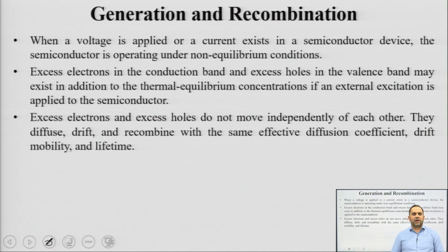Our discussion till now, whether related to carrier concentration evaluation, identifying the current components, polarity, or mobility, has focused on the condition of equilibrium. When we mention equilibrium, we are generally talking about thermal equilibrium, where the semiconductor does not have any external energy available except thermal energy. In such a case, the law of mass action, n dot p equal to Ni square, is also valid.